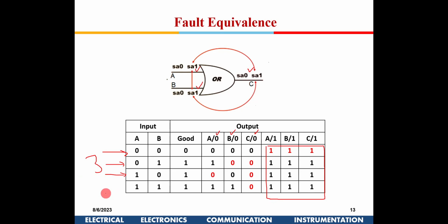My question is, if we already know that C stuck at 0 is getting detected, do we need to check for B stuck at 0 as well? That we will learn when I do random test pattern generation. Say I take 10,000 faults. For the first test pattern I will run, the moment I encounter a fault, I will suspend the run, then move to the next.